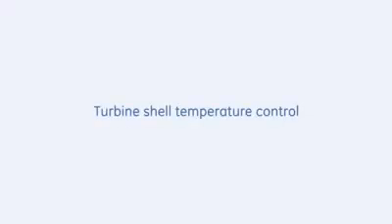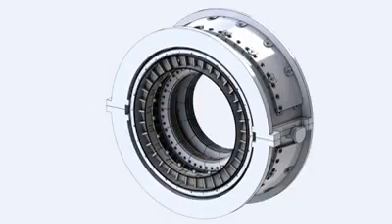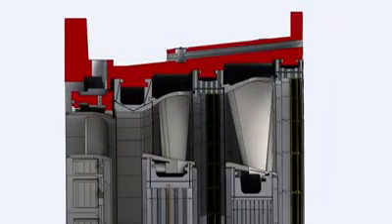For efficient gas turbine operation, clearances between all rotating and stator parts should be as tight as possible. As the turbine shell controls the radial and axial position of all turbine stator parts, the shell should be isolated from the high temperature of the enclosed hot gases. This will ensure the control of the shell diameter and roundness is maintained. The heat transfer from hot gases is reduced by the following means.